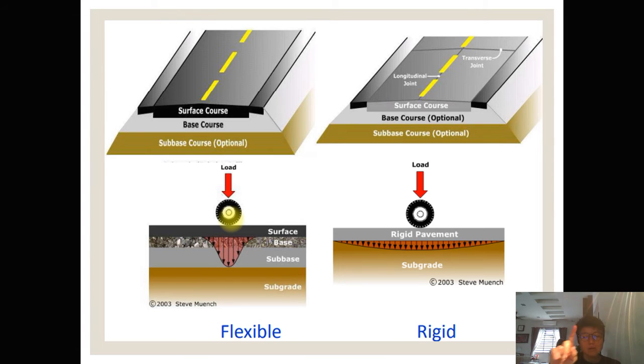When the tyre load comes onto the pavement at one single point, the pavement will slightly curve according to the load. The load distribution pattern is a curve, almost like a parabolic plot. Can you see that? It is rather concentrated at that particular point. When the tyre moves away, the load is removed, and the part that went down will rebound. That's the whole point of flexible pavement.